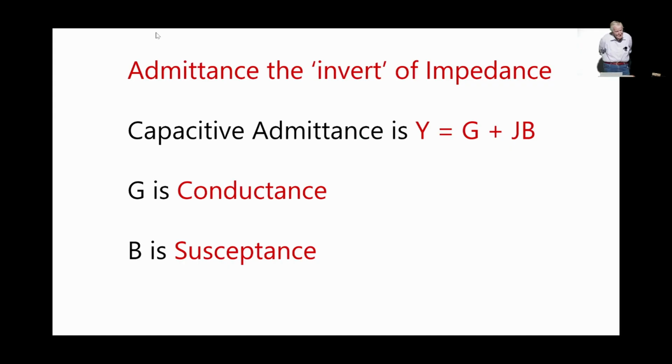Why am I saying this? Well, we're going to be dealing with susceptance and admittance while we're dealing with the Smith chart, because when you're dealing with series networks, R plus jX and R minus jX is the easiest to deal with. But if you're dealing with parallel networks, then the conductance and susceptance concept is easier to work with. And it's just got to do with the sums. You can do either, and I'll show you a couple of examples that are a bit horrifying.